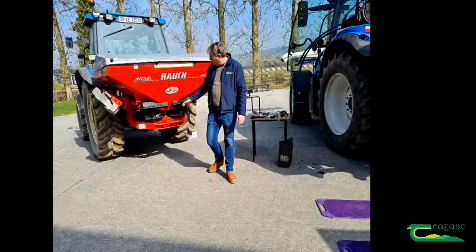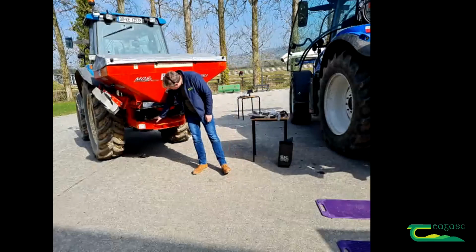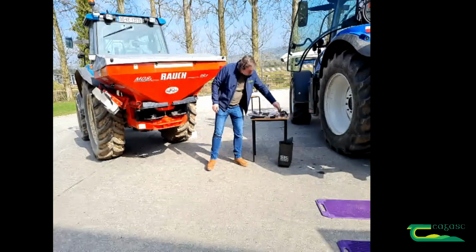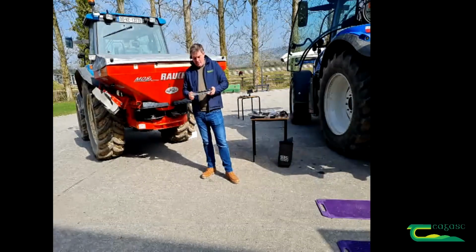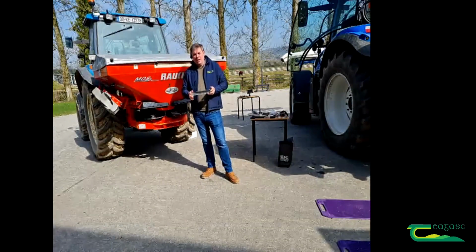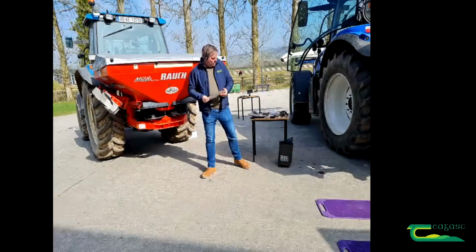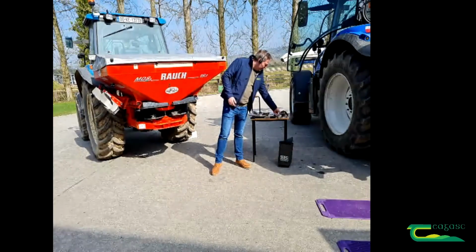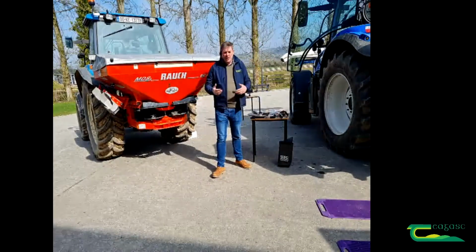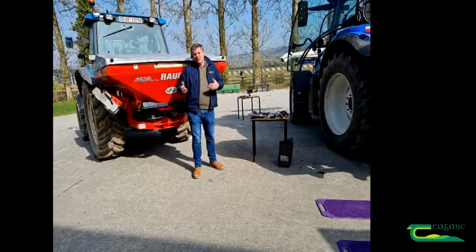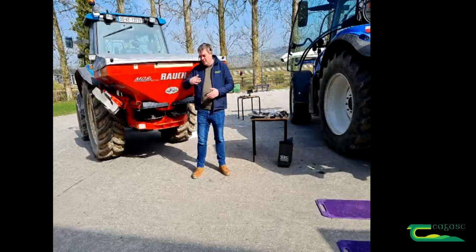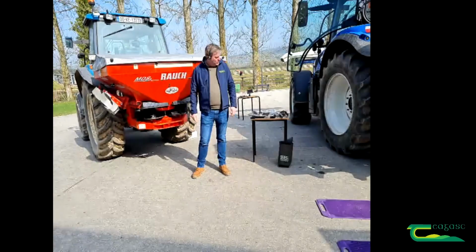And remember, we're relying on these discs, and essentially just that vane, 6 inches or 200 mil of steel, to broadcast that fertilizer, anything up to maybe 30 meters in some cases. Liam mentioned the vane itself being in good quality, but we also need to make sure the vane is set up at the right angle. And the more we change that angle, the more of an effect it's going to have.